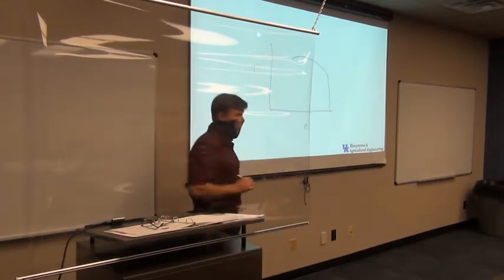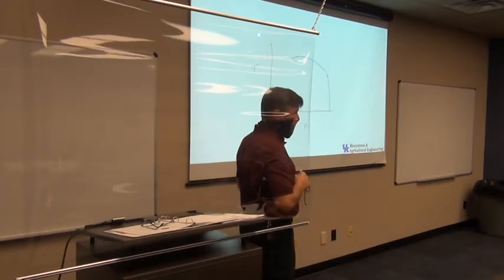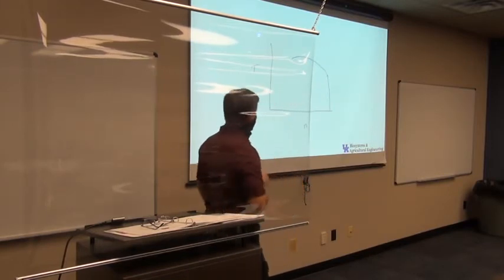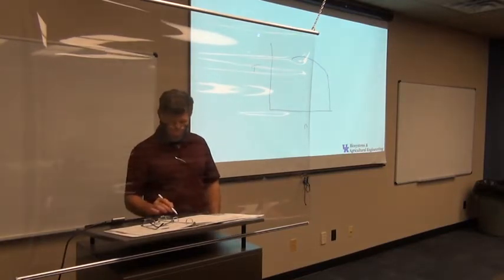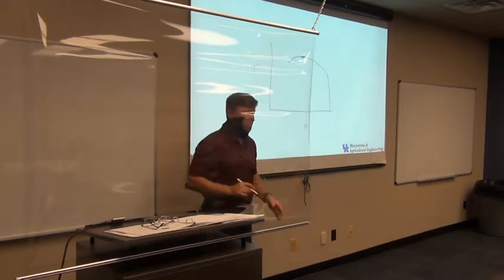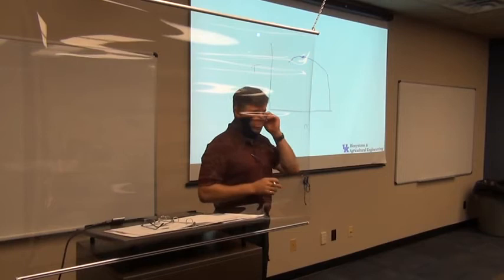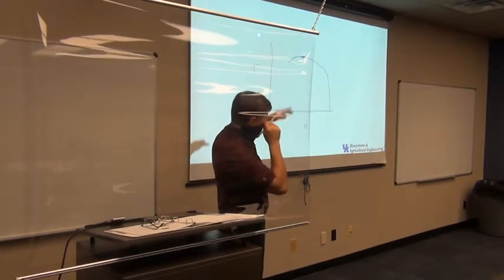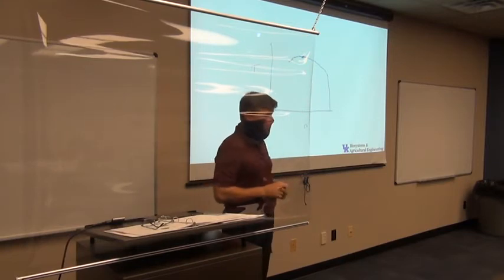Now, most of you had data that looked pretty good like that. I've seen a couple of data sets. Most of you had a little trouble. It's hard to get this data experimentally once you pass this peak torque point up here. Once you hit your peak torque and you're trying to roll off to the left, it's really hard to keep the dynamometer going without the engine stalling, and so most of you have data going up to the peak, and that's kind of the end of it. So that's what you looked at, okay?